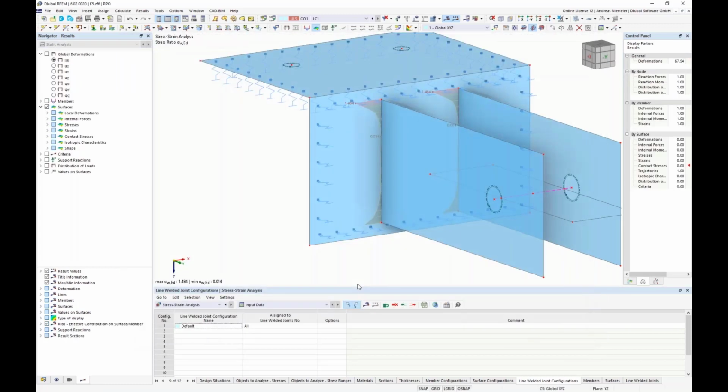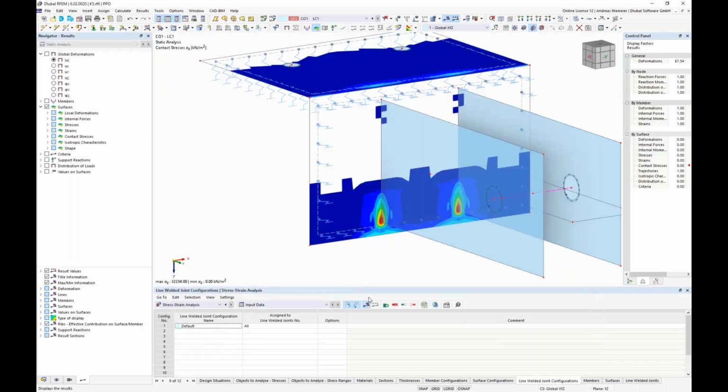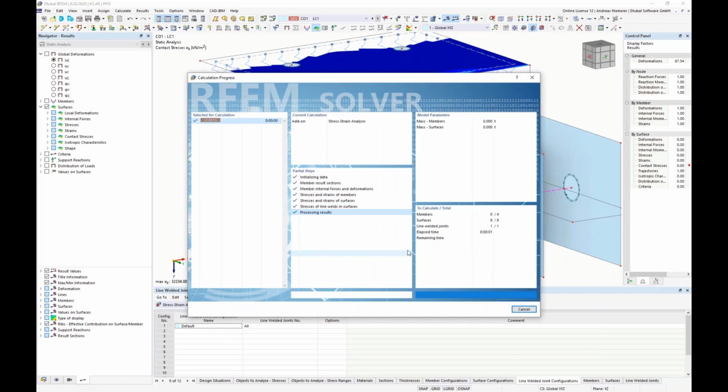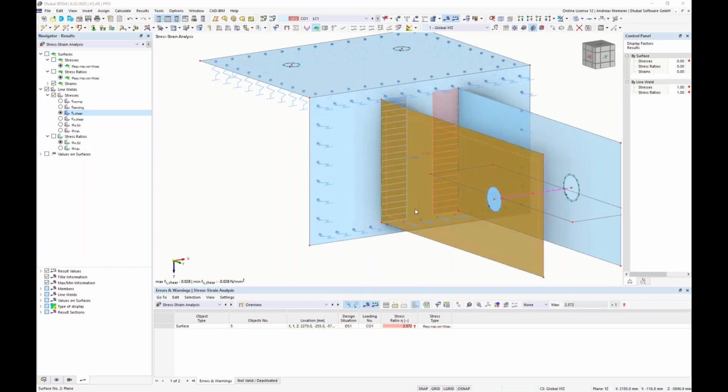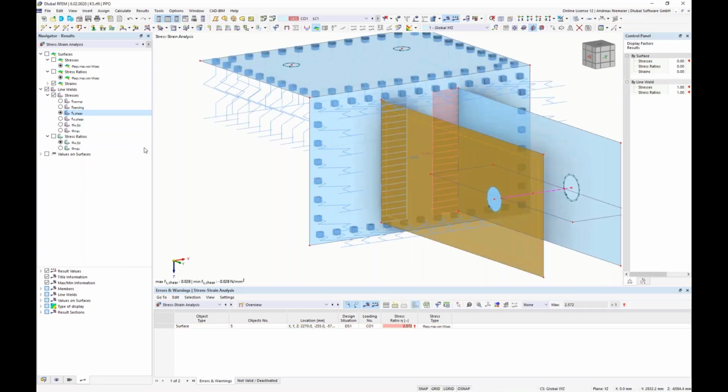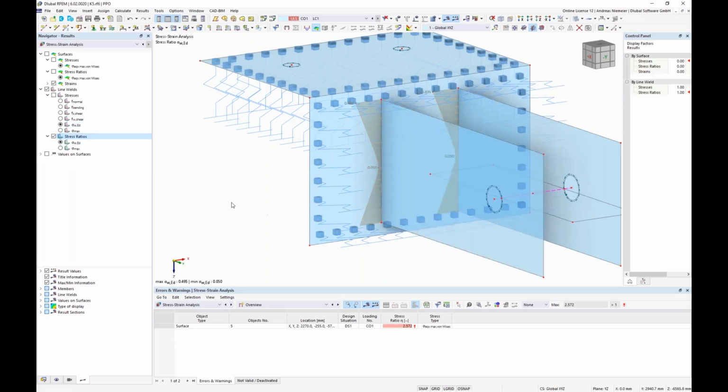And if you check this and recalculate the stress strain result, you will now get, let's say, a suitable result, because the shear load is now constant. And the normal load will be distributed linearly, and this results in a better utilization, and you can do the check. But it really depends on which stresses you use, whether smoothed or not smoothed.